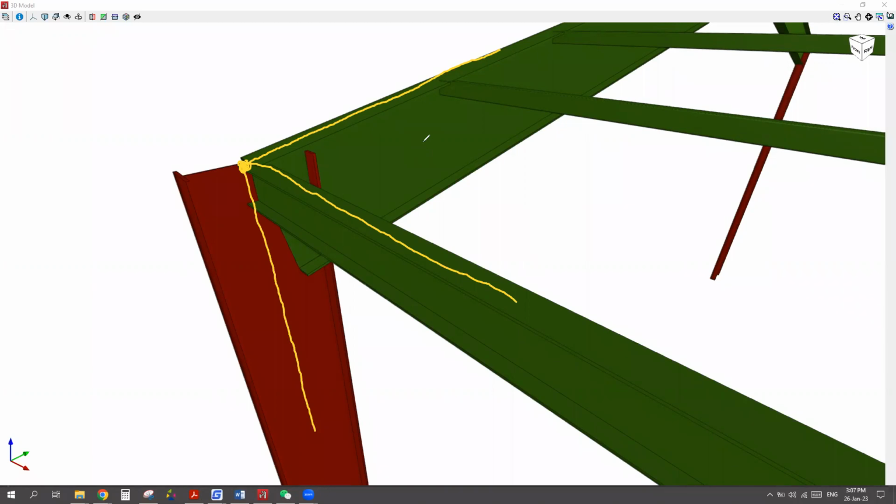Okay. But as you said here, since we shift down everything, I also need to put the purlins here at the top. So what I need to do, assume that you have the purlins, and if you select the bottom center, the purlin actually will be shifted up, and the new location will be like this. You need to select the bottom center. Okay, so let's do it.